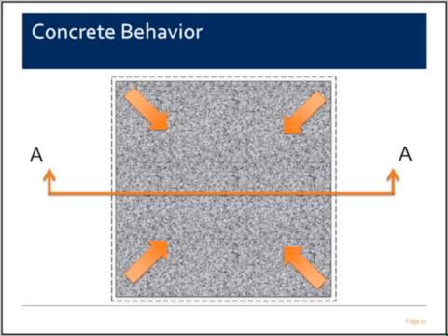Now let's talk a little bit about concrete itself as a material. It is a great material because you can mold it into any shape and pretty much any thickness, but it has its quirks. It's not dimensionally stable after you cast it, after it hardens. Initially, it shrinks due to surface tension of water in the capillary pores, and then later by loss of absorbed water on the surface of the capillary paste. It may also shrink due to carbonation, but this is very little compared to the other two. It not only shrinks, it also creeps, both in tension and compression. But let's forget about it for this discussion.